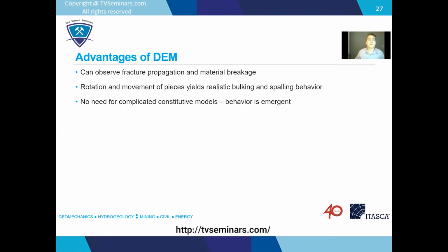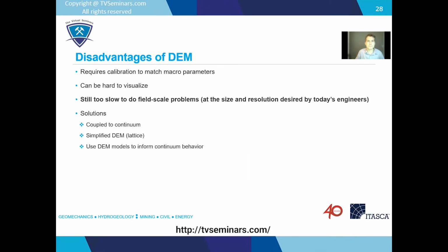So, advantages of the DEM method. You can observe fracture propagation and material breakage. The pieces have the potential to actually rotate and move, and this can give you fairly realistic bulking behavior or spalling behavior, kinds of things that are difficult to simulate in a continuum model. And again, you don't necessarily need to specify complicated constitutive models.